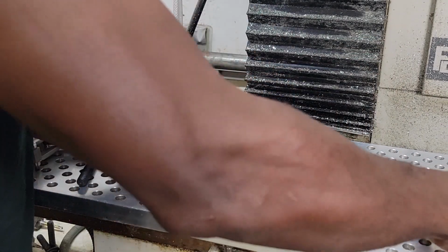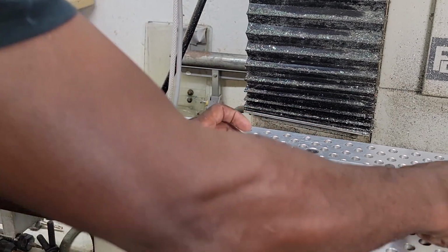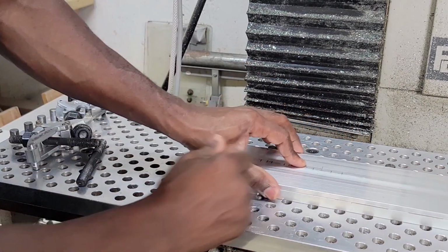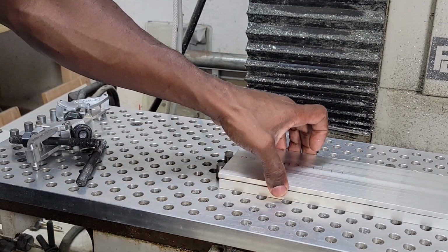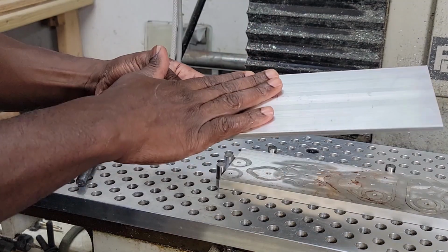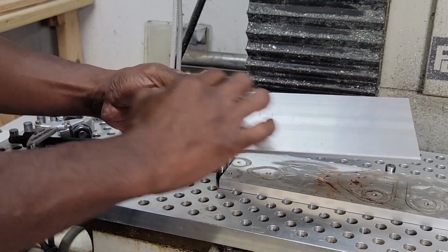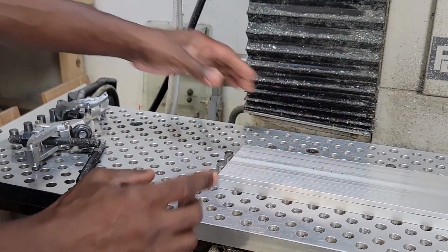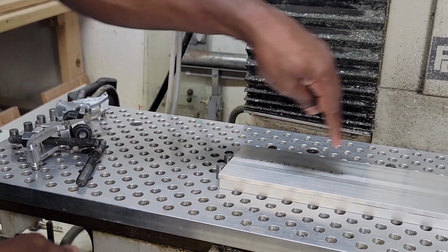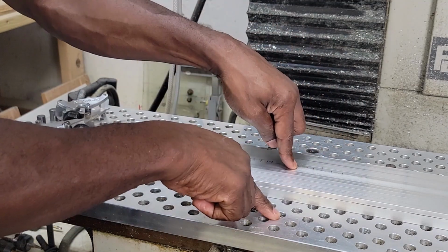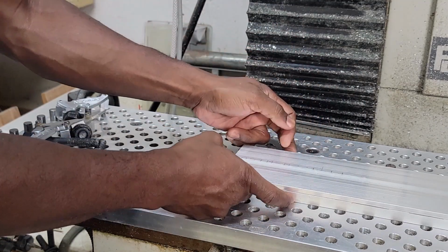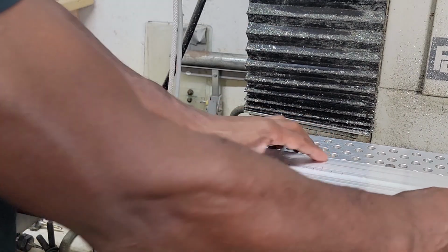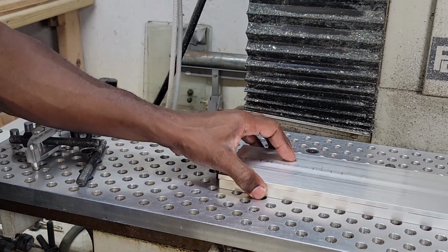Okay, this is good. So I'm going to bank it over here and on those 2. So now I have my 2 plates. So the thinking here is, this is my workpiece. So after I machine the first passes, I'm going to use screws to hold down the workpiece. I'm going to screw it onto the bottom piece so that my parts don't fly off as I machine them. So that's the logic.